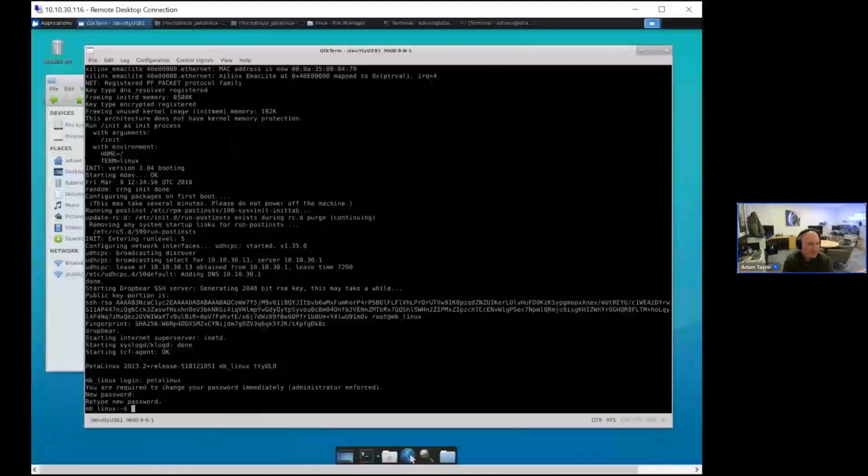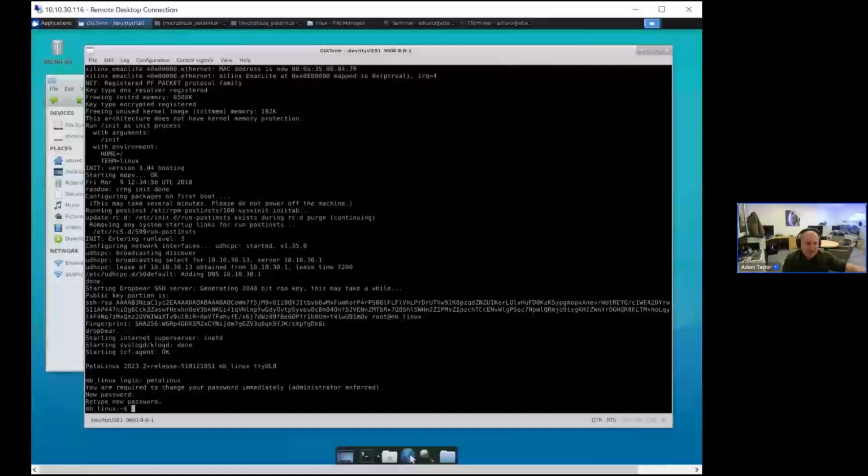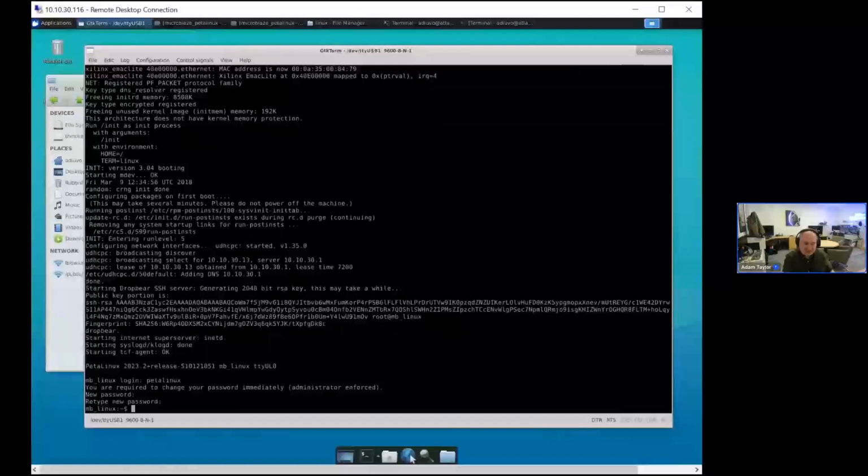With a little bit of code in Vitis, I could write down the I2C sequence to configure the clocking chip such that it gave out the output. I could then see the Ethernet PHY spring to life and the LED started going and everything.